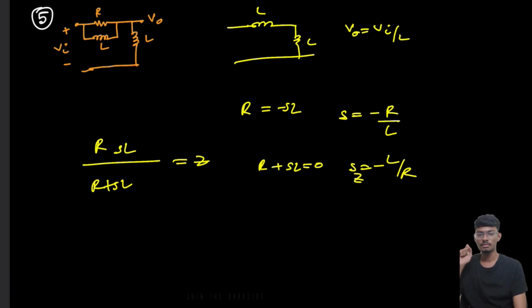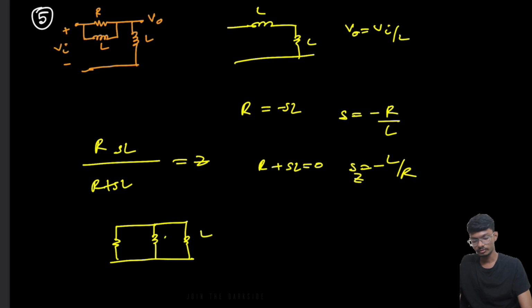Now let's go for the poles calculations. For the pole, what we have to do, we have to basically make infinite impedance up here. So what is the equivalent impedance we are seeing? Again I'll solve from the other method. So what we have to do is adapt from circuit to circuit which method is suitable for that particular circuit. This is V0 and these three are in parallel, right?